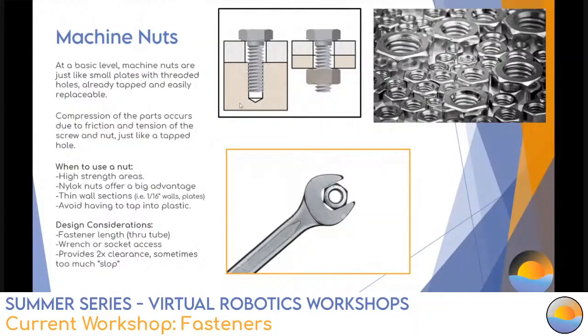And a little more engineering principle here is that if you look at this, when you use a nut and bolt here, you actually have two plates now that have clearance that are necessary, that I talked about being necessary earlier, but now you start to have a little bit too much clearance. You have 2 times the clearance for a normal hole. So then it starts to get a little bit more sloppy, and you probably want to consider other means to precision align those holes.